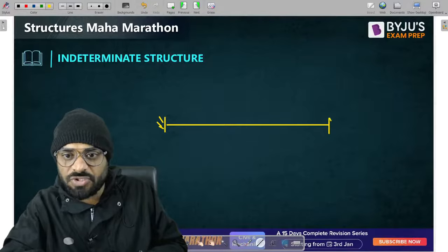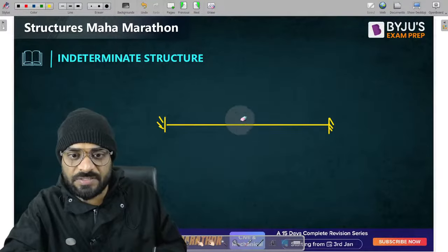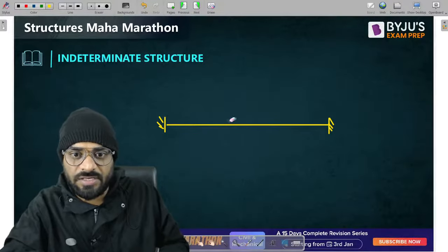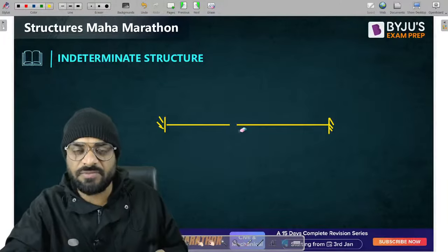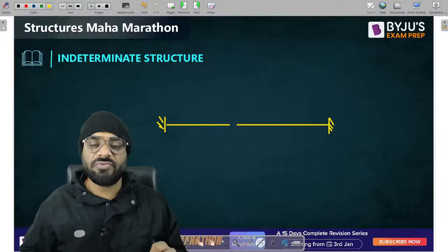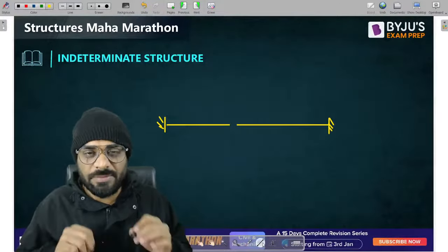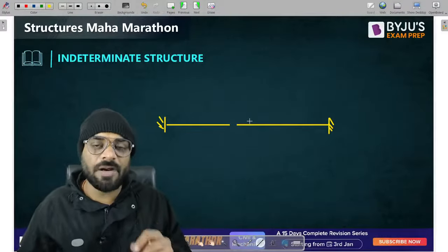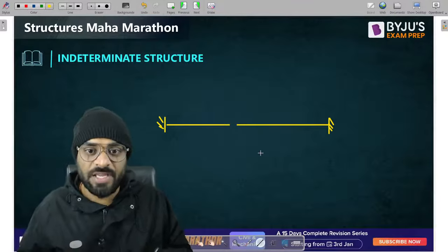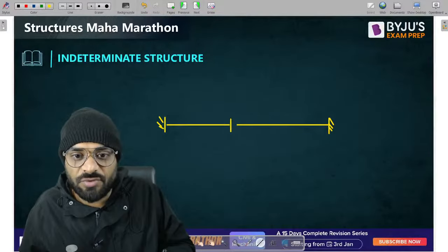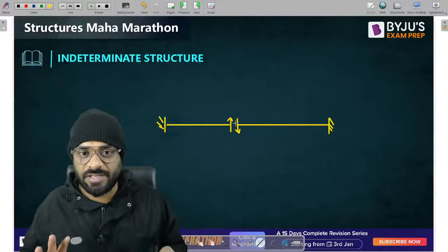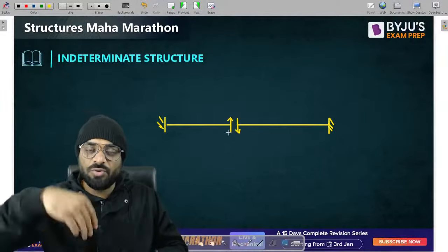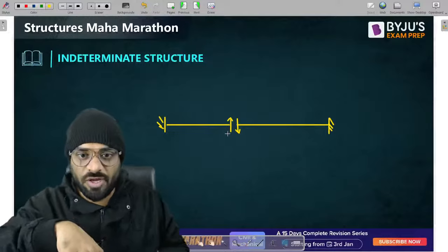So guys, for shear force at C, you need to break the structure at section C itself. Now, in this case, why are we using two arrows? Tell me guys, if you take a section on the left part and on the right part, we may have the shear force. And that is the reason you have to use this standard direction. Please remember this is a standard direction.